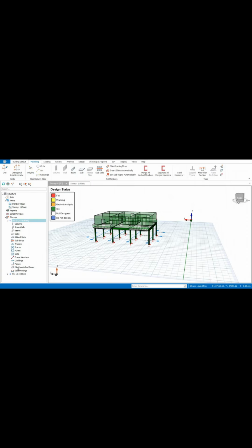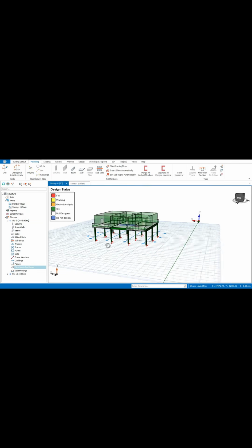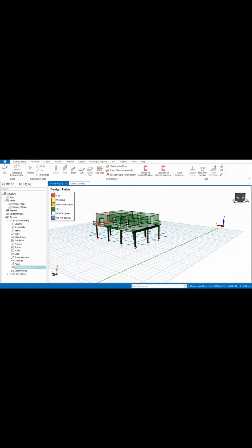Then we can actually go down here and insert a pad and pad base. You also have the option of strip here, strip footing here, but we are not going to be doing that today. So what we're going to be doing is we're going to be inserting a pad foundation right here. We're going to be inserting a pad foundation, and you can't do that in your 3D mode. You can see that as I'm clicking it, it's not going. So you need to do that in your plan.